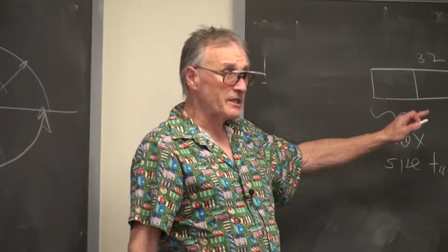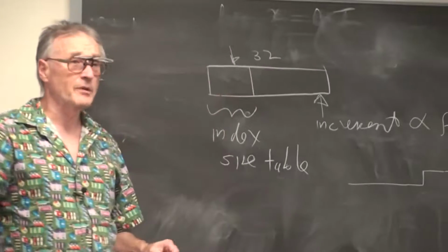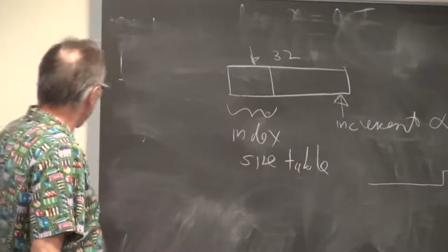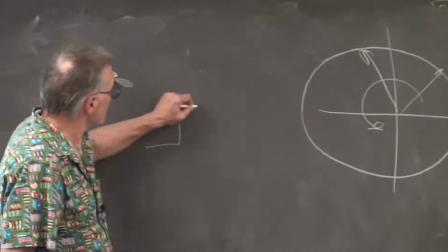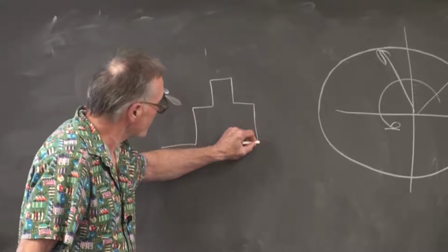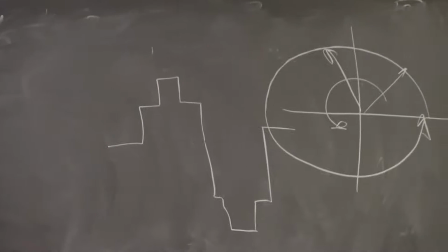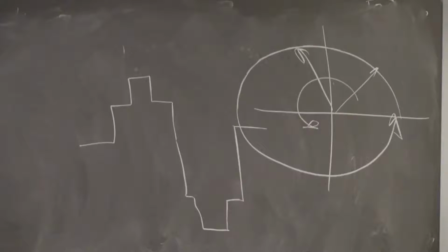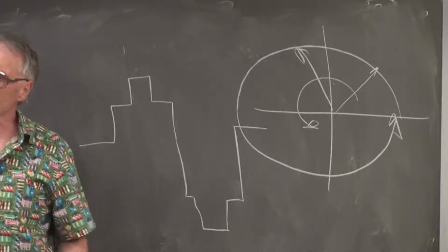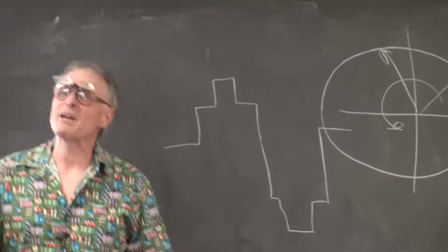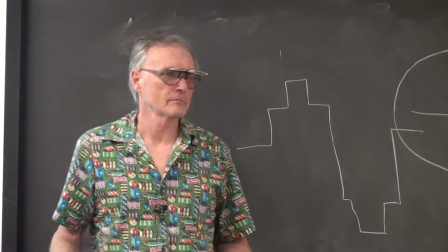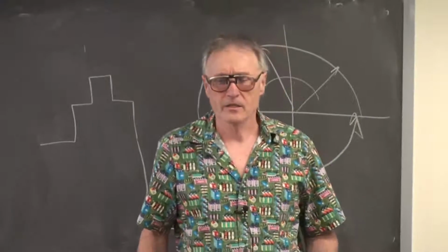At very high frequencies, where the increment is going to be up here someplace, you might have a sine wave that looks like this. Clearly there, the distortion is going to be so high that you'll be able to hear the difference between the waveform and a pure sine wave. And so one of the homework questions asks, how many samples does there have to be on one cycle of a sine wave before it's sufficiently sinusoidal?